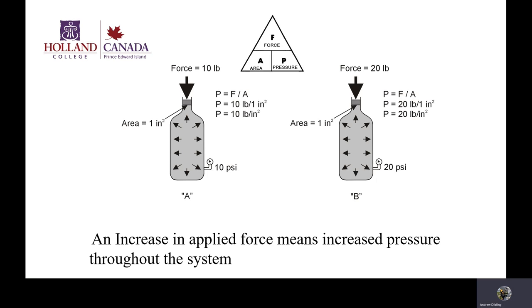So if I'm looking at a hydraulic cylinder or an accumulator that I'm going to change out on a wind turbine system or other large hydraulic system, and I see that the gauge says 200 bar, I know that the amount of pressure within that enclosed cylinder is 200 times the atmospheric pressure.